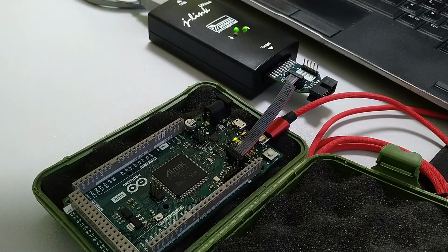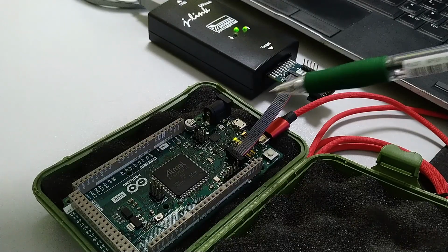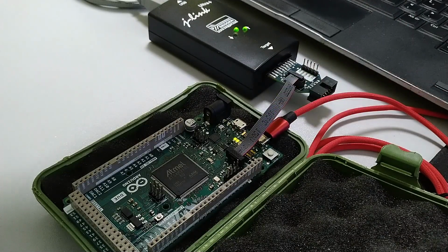We're back with the Arduino Due, and for today I got a bare-metal project set up. That means we use our own makefile, linker script, assembly startup file, and the main.c. The project will set up the RAM segments, power management, and the PIOB for blinking the D13 LED. I also have a debugger attached, so I will show you what is going on in the RAM segments. So let's get started with the project.